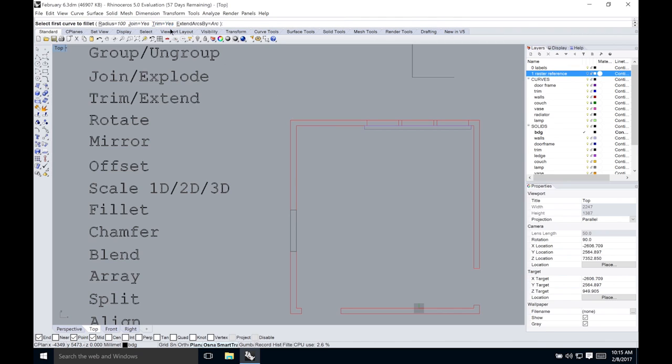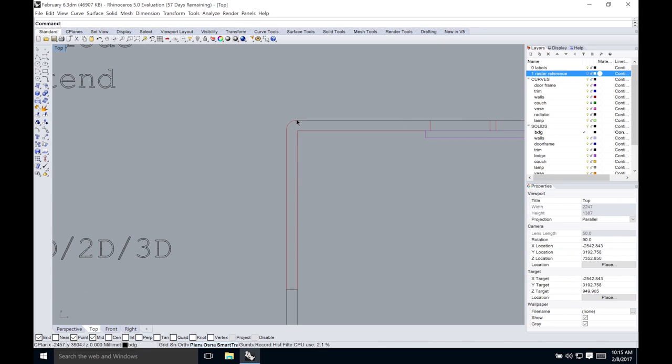In some situations you would have lines that may be intersecting and you want to create a rounded corner from them, so Rhino can trim that. I'll show an example of that in a second too, but let's just leave it this way, and then basically select first and second curve to fillet. And no, so that's an option. So you have to click on that to change it.